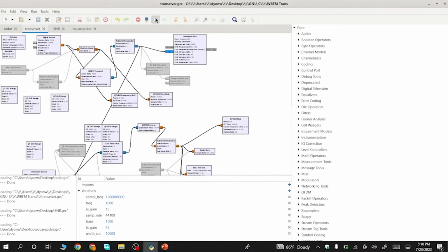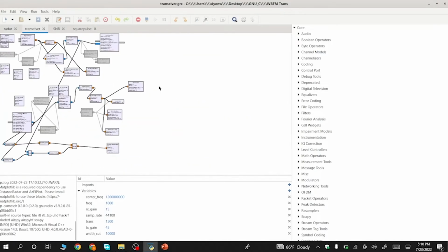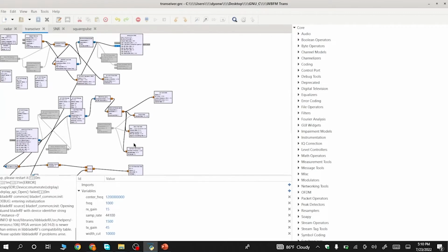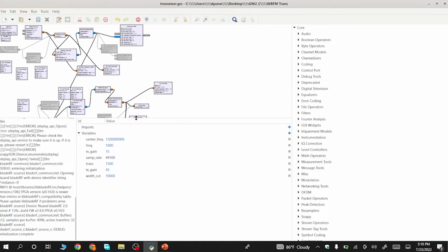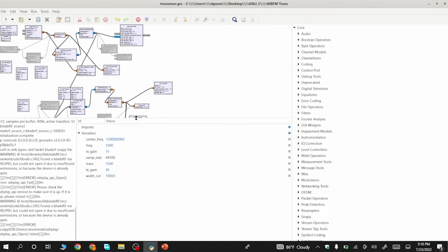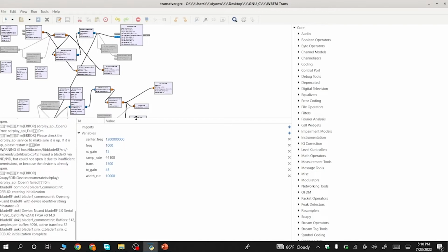We decided to implement our radar system on a software called GNU Radio Companion, which is an open source platform to build wireless communications. Each block you see on screen right now are readily available modules that you can configure to suit your needs. We designed the transceiver we are going to test now, which will send out a continuous signal on the 1.2 GHz radar band and try to receive it with a viable SNR for further signal processing.